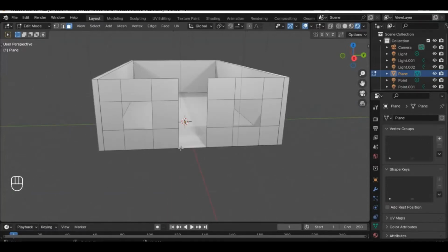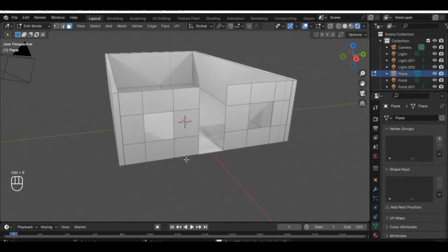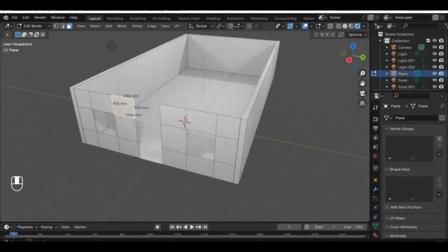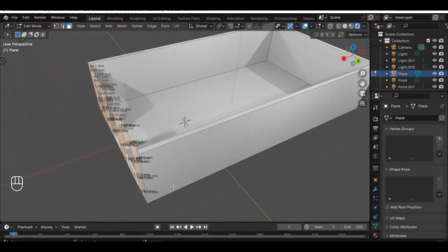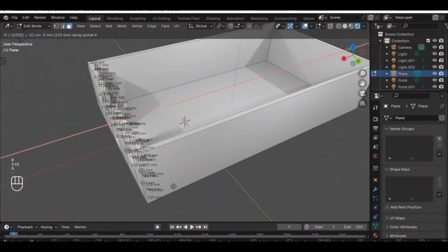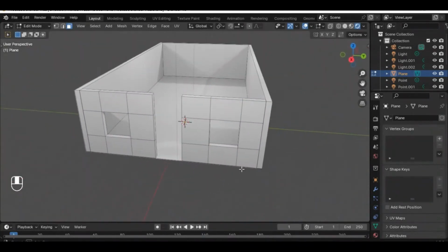So now I'm safe to extrude each and every one of these walls, just like I extruded all of that. You need to pick every face, and because you're extruding in the same direction, you can actually do it once and for all. So let's try that. Extrude Y. We are extruding on the x-axis 2.5 minus, extruding into the house. So now you have this solid looking house. You have a solid looking house right now.